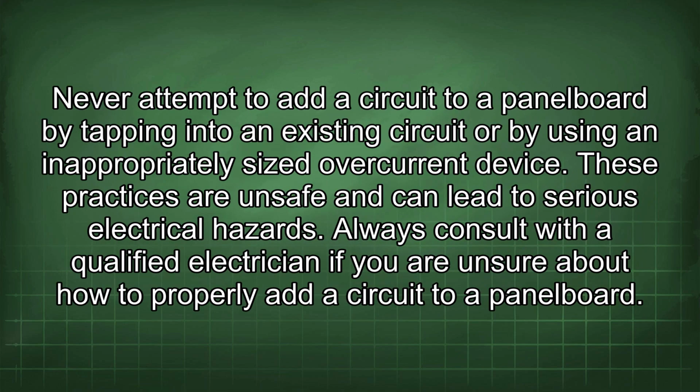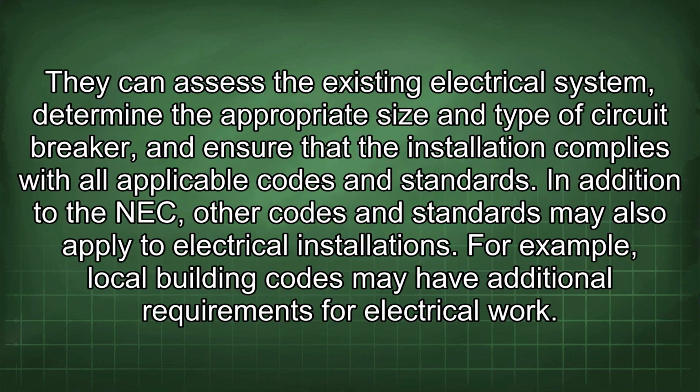Never attempt to add a circuit to a panel board by tapping into an existing circuit or by using an inappropriately sized overcurrent device. These practices are unsafe and can lead to serious electrical hazards. Always consult with a qualified electrician if you are unsure about how to properly add a circuit to a panel board. They can assess the existing electrical system, determine the appropriate size and type of circuit breaker, and ensure that the installation complies with all applicable codes and standards.